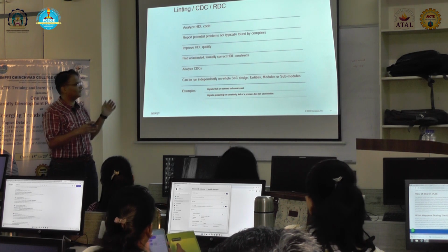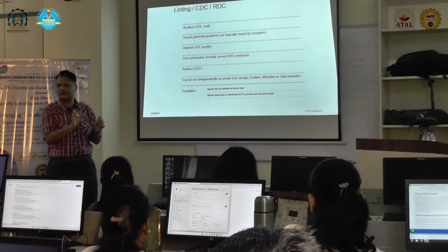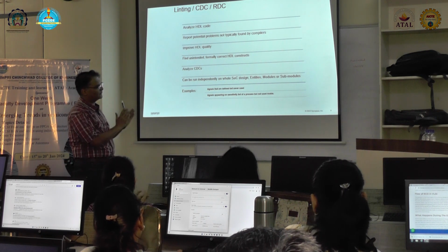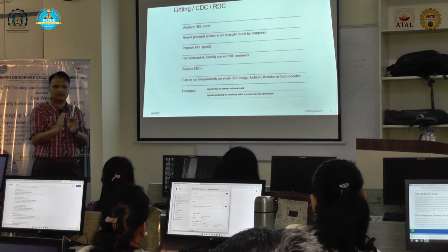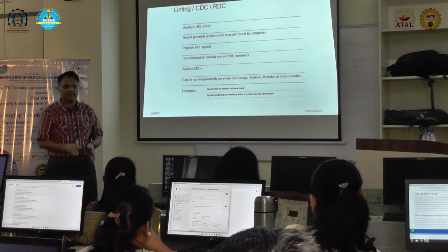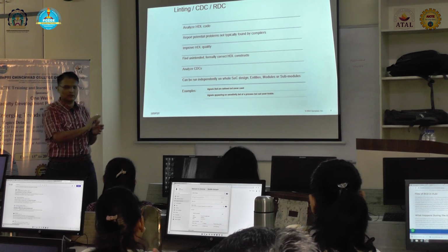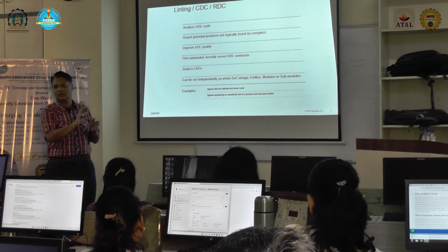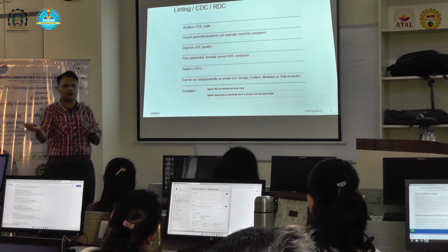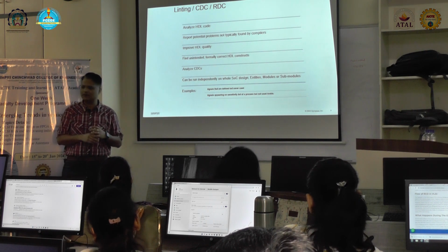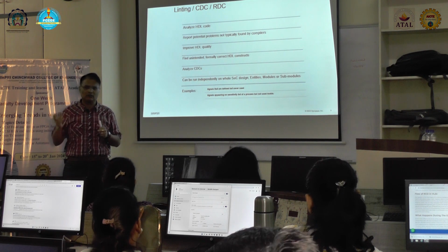Whenever there are two clock domains, let us say we have a design where half of it works in clock A and half of it works in clock B, then we have to implement a synchronizer stage in between for all signals to reliably transfer over into the clock B domain, and then again back from clock B to clock A there is also synchronizer logic.